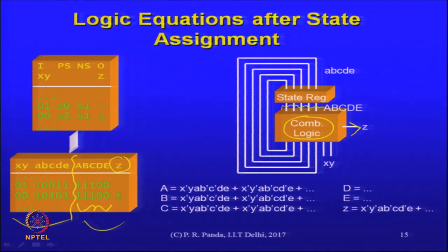So, the truth table of course captures both of these outputs. One is the next state signals, the other is the output signals of the FSM. So, let us build the logic. I have to build an expression for all of these 6 outputs, right. One for A.